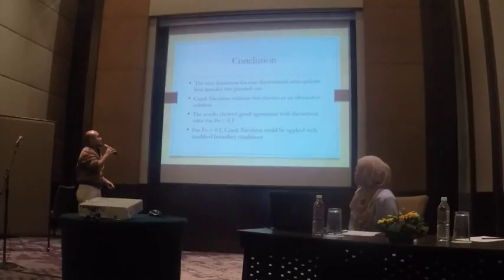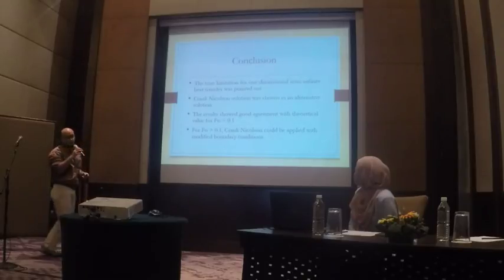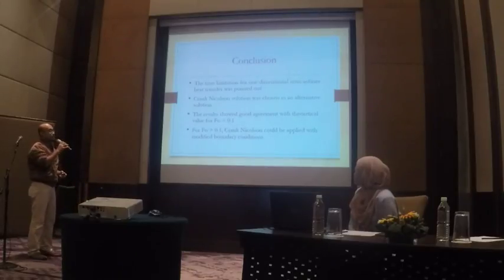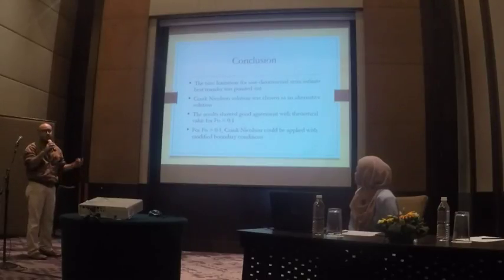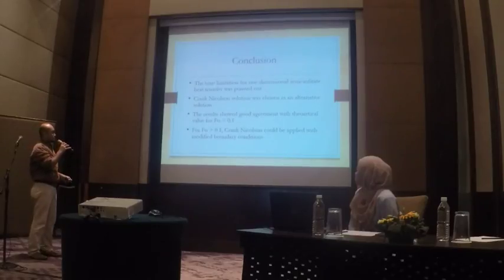So the conclusion is that the time limitation for the one-dimensional semi-infinite solution, which is Fourier number 0.1, is quite short for a heat transfer experiment. And if we can use more surface temperature data above Fourier number 0.1, we can have much more data for the analysis.